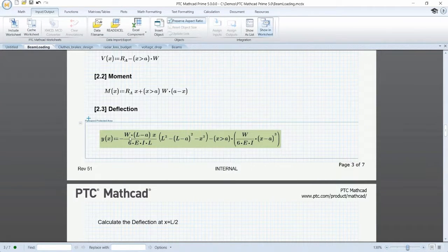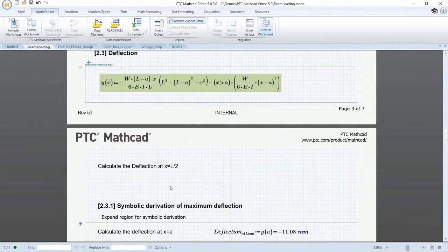So go ahead and leave it expanded, but password protect that area so that if you want to change it, you will need to know the password. Okay, let's go ahead and use that variable that we defined up above right next to that diagram and use the equation that we password protected to calculate what the deflection is at L/2. Again, we change those units from meters to millimeters real quick. Just change that M to a MM and it automatically updates for me.